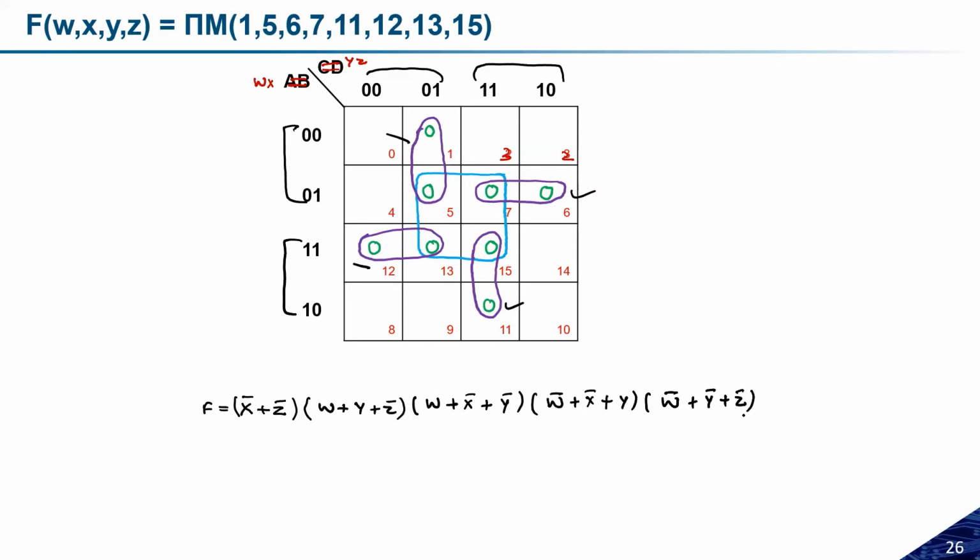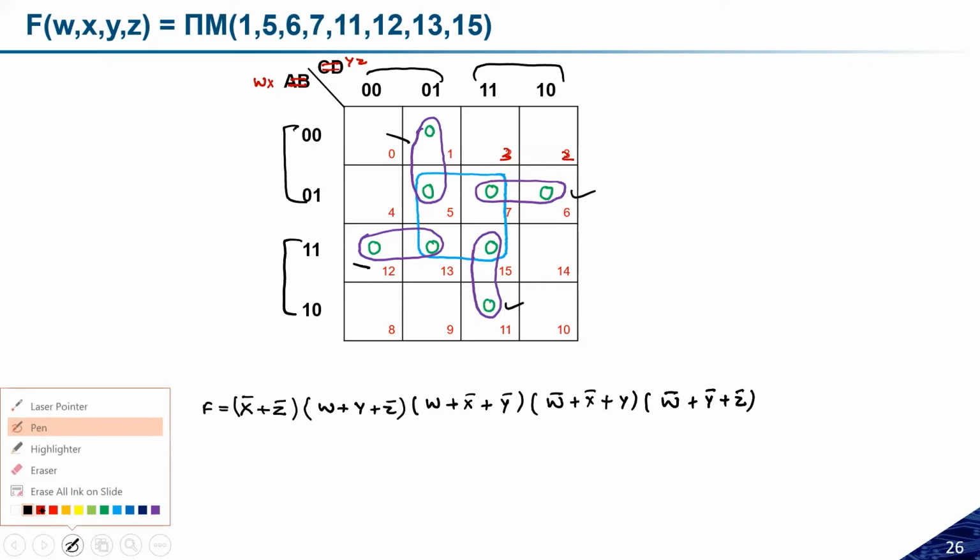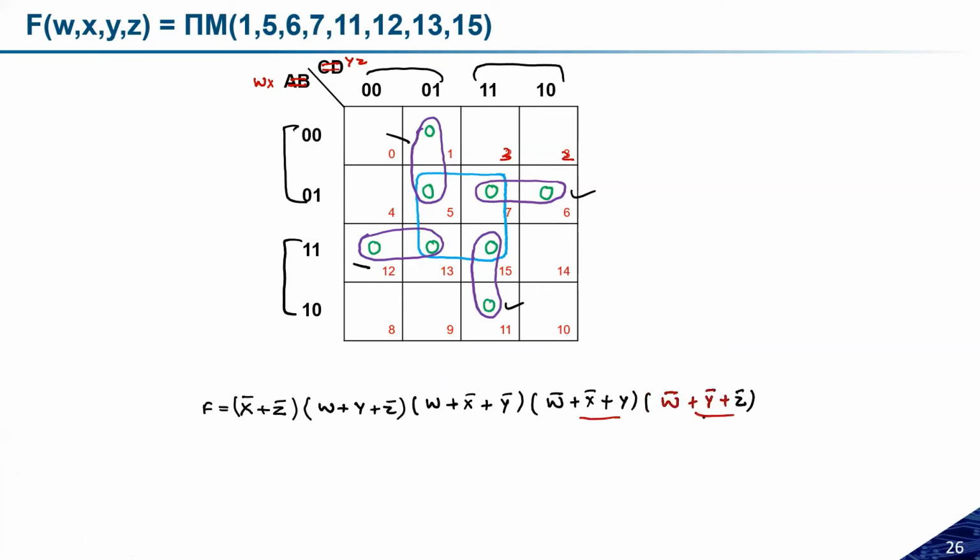Now, if you see here, I have 5 max terms. Okay, so 5 max terms I can see here. One is this one, second one is this one, third, fourth, and fifth one. But if you clearly see here, even though I have made a pair of 4, if I do not consider this one, even in that case all the zeros are considered. So here one rule is very important. I just told you before, I have to make a pair of the maximum number of ones or the maximum number of zeros. That is what we have done, and accordingly we have solved this one.